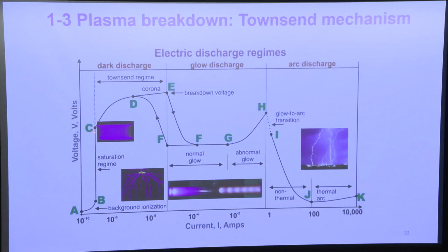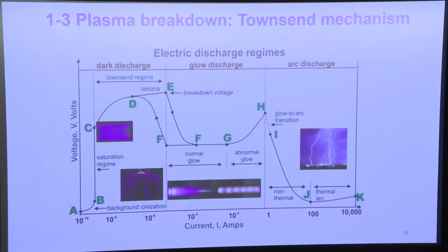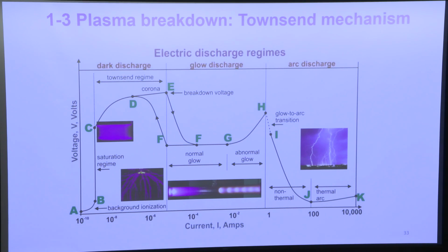But when the voltage becomes so high, some of the electrons accelerate, gain energy, and start to collide with neutral molecules. They start to become a Townsend regime. That means an electron collides with a molecule and generates 2 electrons. That is the ionization process. They call it Townsend. So this ionization process increases the current, and at the same time the voltage increase is decreased. At a certain point, the voltage becomes so high that a streamer flies from the electrode into the mixture.